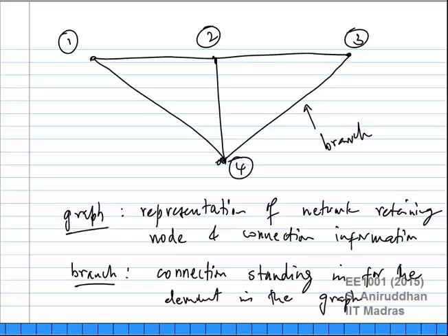It also holds the potential difference information. You can define the voltage of each one of these nodes. Just because this is not a wire, this is just a branch. Remember that this is not a wire in the graph. It doesn't mean the potential difference is 0. So this graph has the voltage and current information that you need. You need to extract that out.